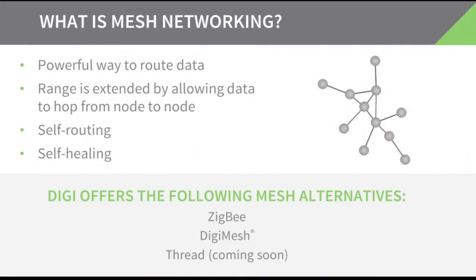Before we talk about mesh, let's just do a real quick review on point-to-multipoint. In a point-to-multipoint or point-to-point or even a star network, as these are sometimes called, every radio has to be in direct RF communication with every other radio in the network. So in this case, radio A can only talk with radio E, D, and B. F, G, and C are out of range and not able to communicate. So typically in this kind of configuration, we often put a radio module in the middle where D is, with surrounding radios to communicate with, and this is what we call a star topology.